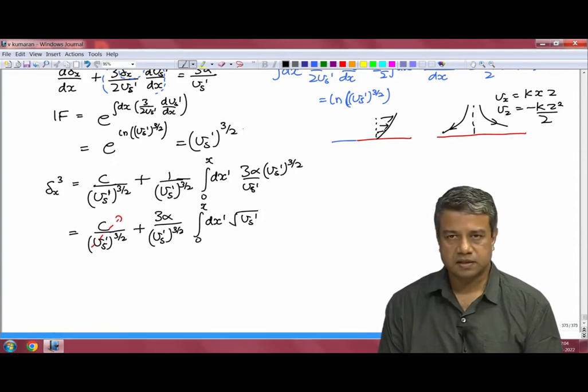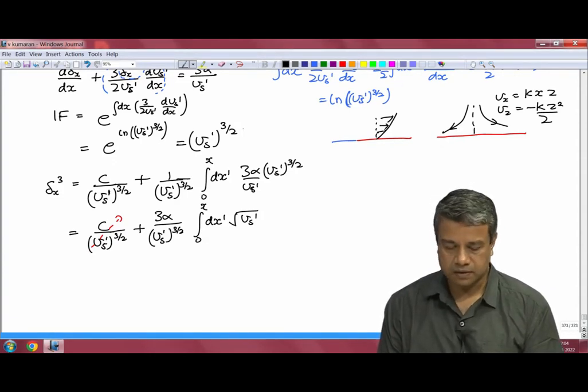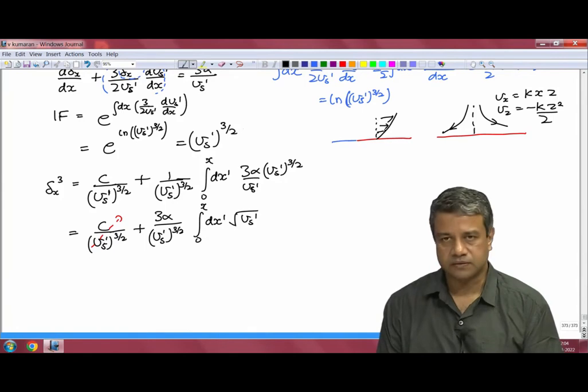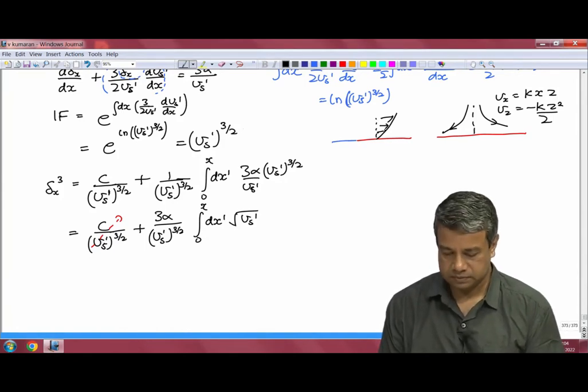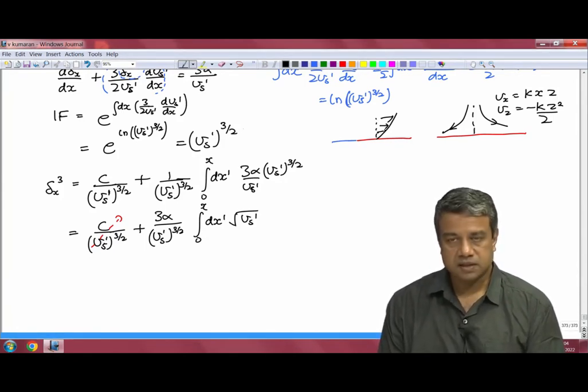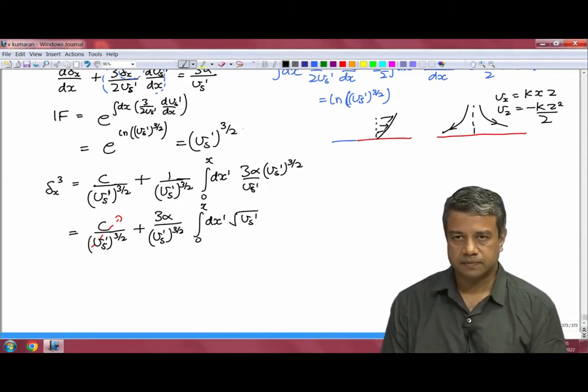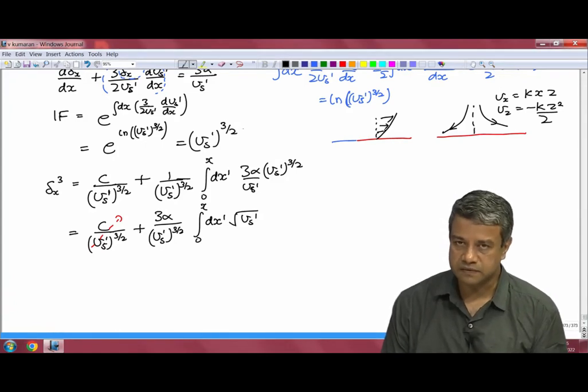And in both cases, you can use this formula in order to find out what is delta cubed and therefore delta, and then integrate that. I will not go into the details, it is a straightforward substitution. The same formula does not apply for the flow around a sphere, for example. The reason is because the equation for the velocity profile is different in that case.